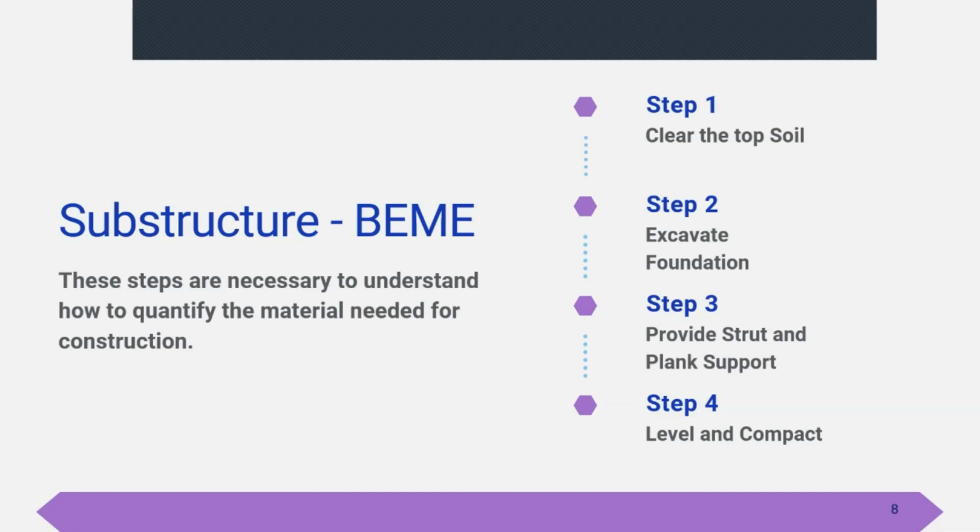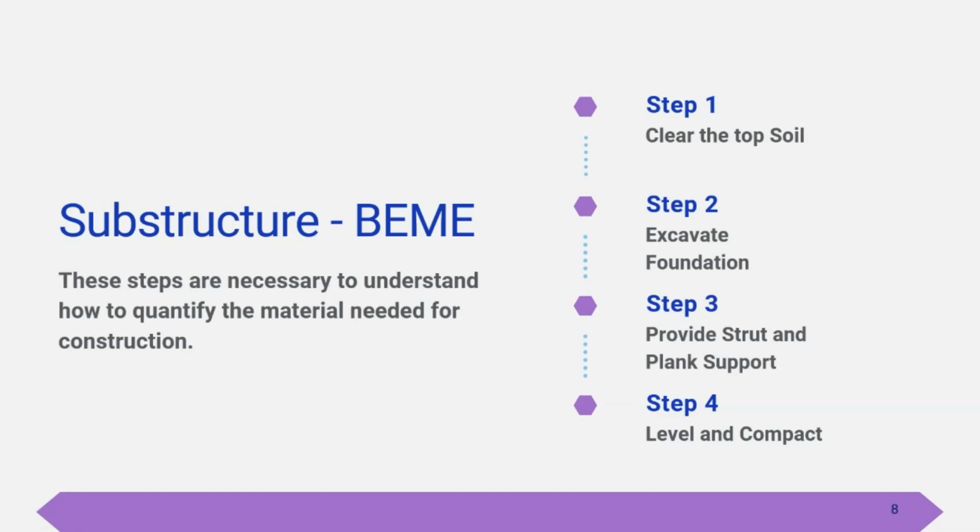So moving on, in this case, if you check the question, but let me just explain the procedure so we can check the question later on. In this case, we are working with a virgin ground that I am going to for the first time to construct on. So the first thing I need to do is clear my topsoil, just like cutting the grasses. The main goal of doing this is because I want to construct a foundation for my generator house. Do you understand? My generator house needs a foundation so I can put it on. I am not working with the superstructure, I'm working with the substructure.